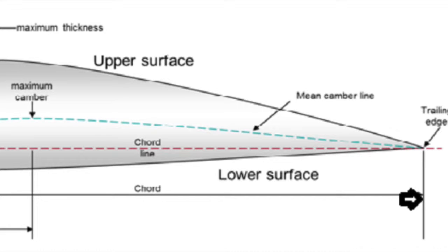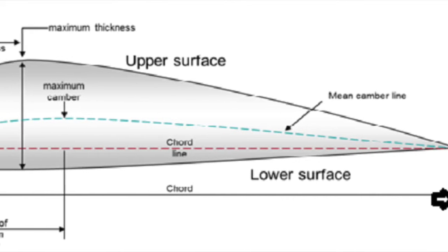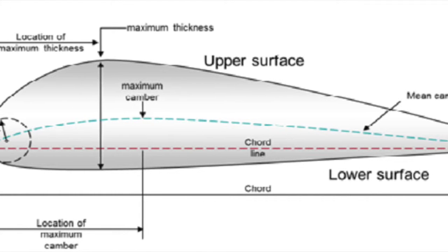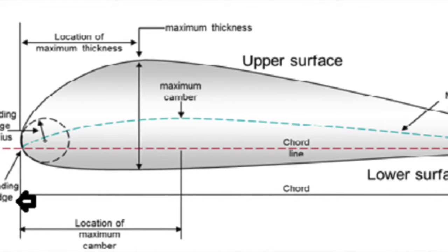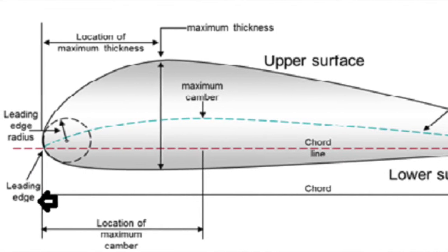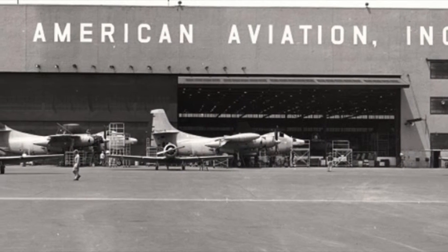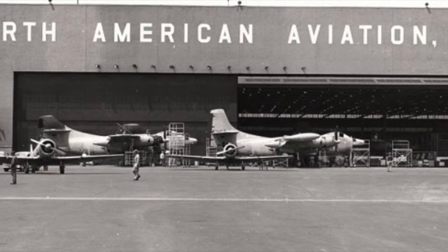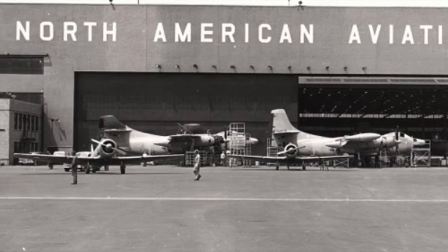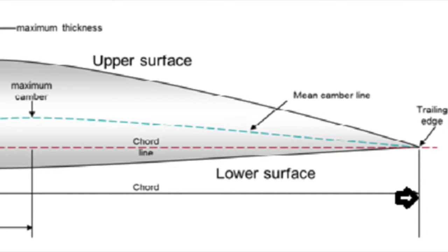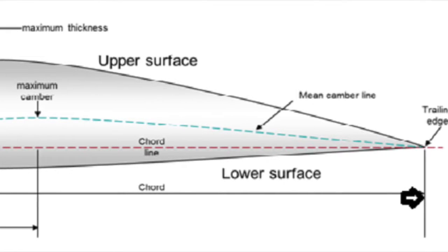The use of an airfoil on the Mustang would greatly add to the drag-reducing concept. Because the Mustang wasn't capable enough to efficiently produce laminar flow, engineers at North American Aviation (NAA) approached this problem with a plan to fill and paint the wing surface to provide smoothness, allowing the air to move in a fixed pattern.